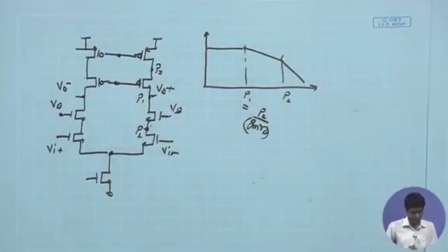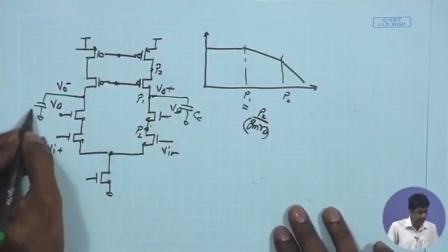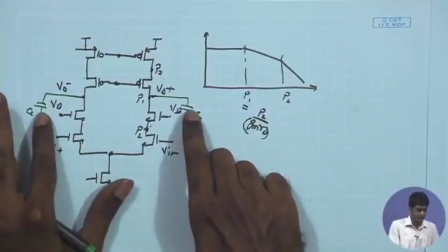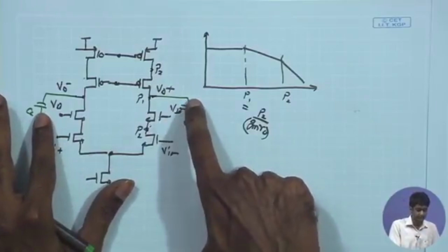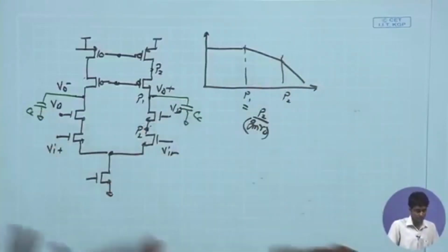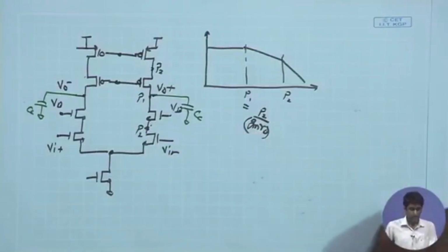So whatever additional capacitance I put at these nodes, I can call this CC, or it can come from the load capacitance of the next stages. There I need to make sure that the ratio of this CC and the total capacitance over here is close to the gm*ro factor, and it is not very difficult to achieve.